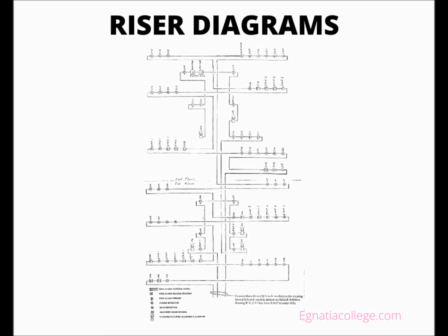The school edition drawing E2 shows 3 3/4 inch conduits with the note 3/4 inch existing conduits from the fire alarm control panel, 150 feet. These 3 conduits are to be used for the school edition fire alarm connection to the existing fire alarm system.